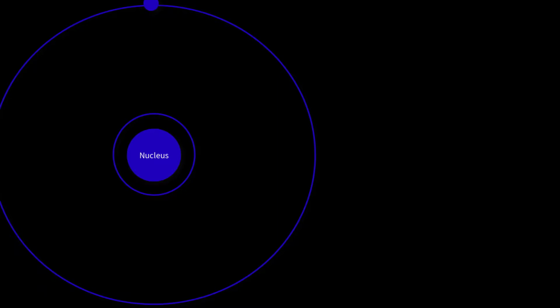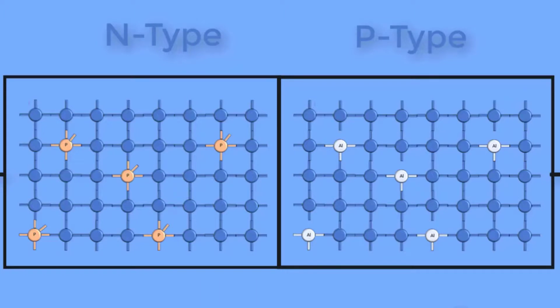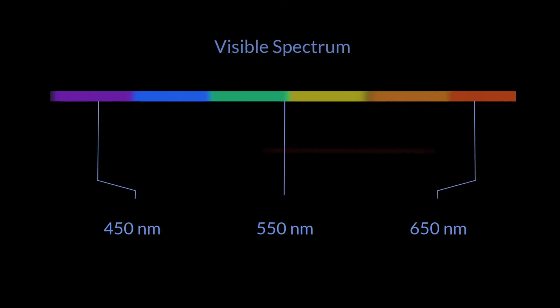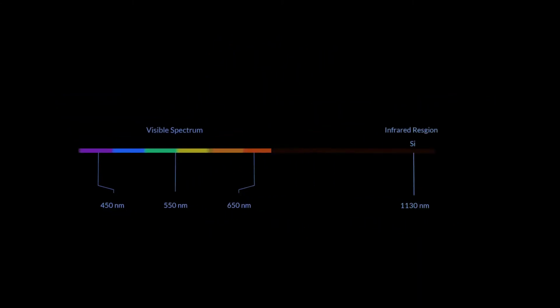Blue light has a short wavelength and red light has a longer one. The radiation emitted by a silicon diode is not visible since it falls in the infrared region. However, using gallium causes the radiation to fall in the visible spectrum. That is, the diode emits light.